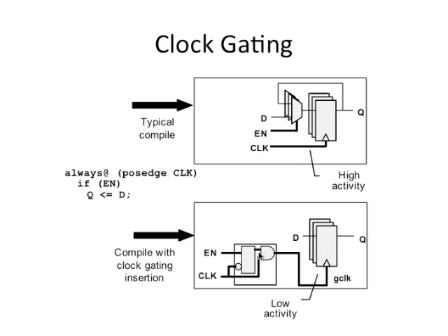After that, it remains stable. That is the property of a negative edge triggered flop, right? So it remains stable till the next negative edge, and it will change only after the next negative edge has happened. So I am assured that during the time the clock is high, this other input of the AND gate is stable, and so I won't have glitches. So just a simple guarding circuit.